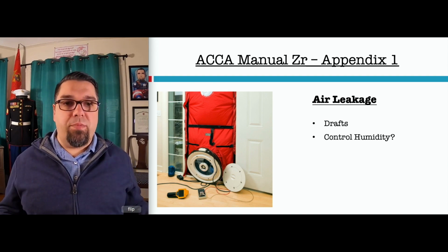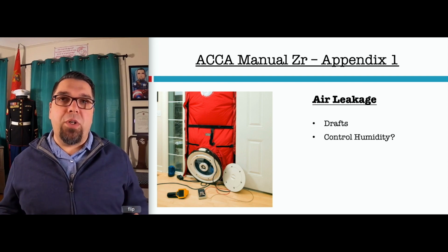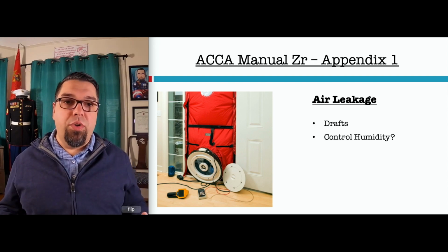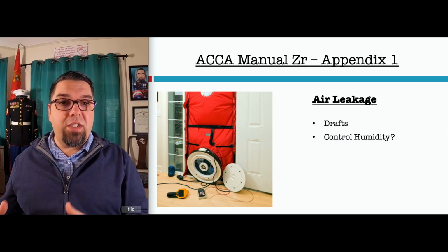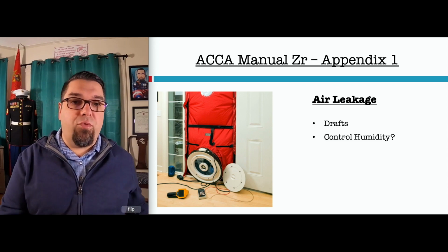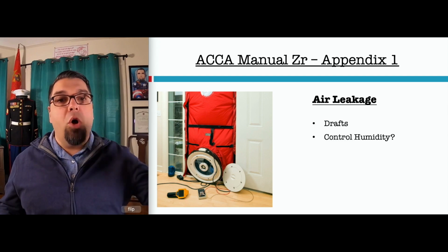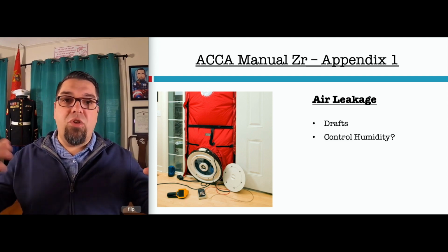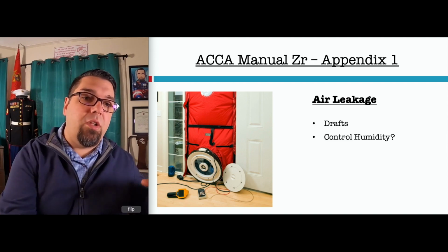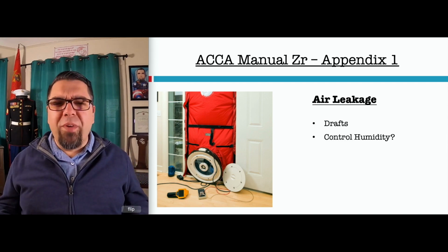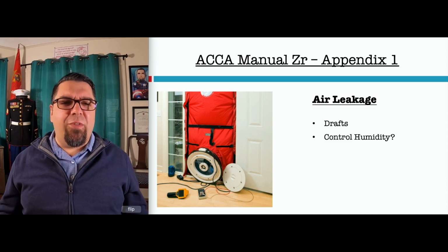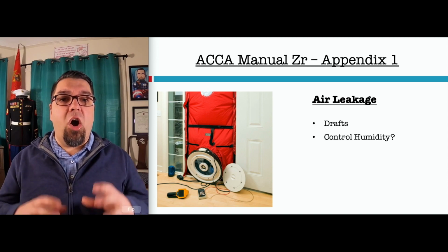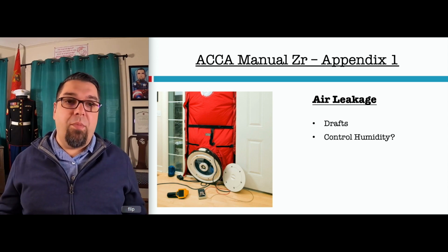Just like temperature goes from hot to cold, moisture goes from high content, high relative humidity to low relative humidity. So if you're bringing back lower relative humidity air from upstairs and you're sucking in high humidity, obviously that moisture is just going right into the return duct. See that a lot with open filter slots, things like that around the furnace. You want to address any obvious stuff that you can see into the ductwork. Do that first.